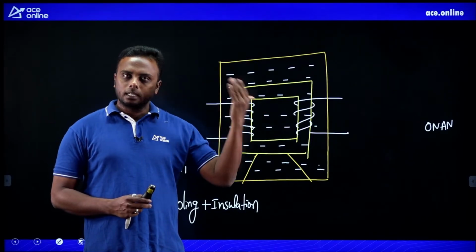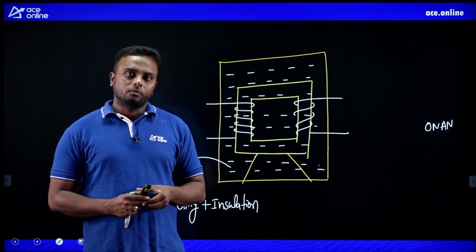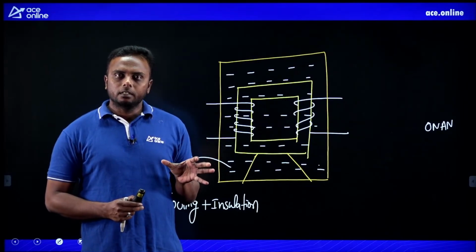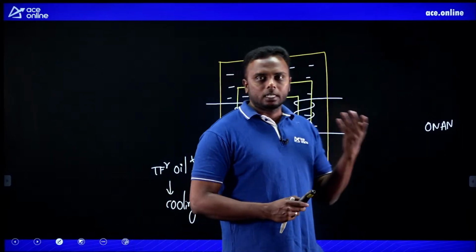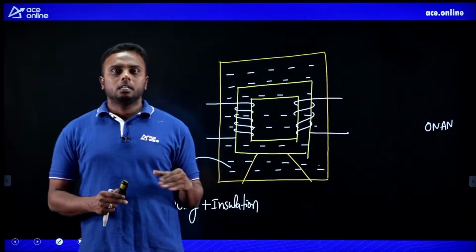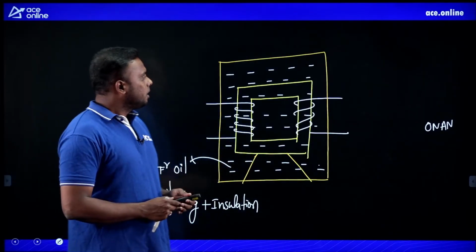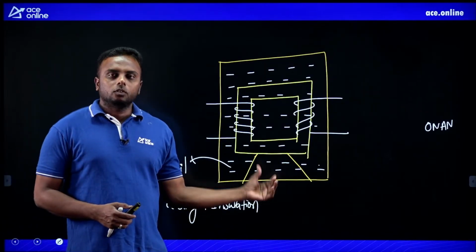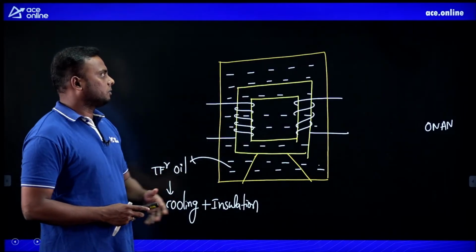But if you go to higher level transformers, power transformers with very high ratings, like 100 MVA, 10 MVA, 20 MVA, there we definitely need effective cooling, particularly at high voltage. Power transformers belong to higher voltage capacities, so they require better cooling than distribution transformers. Okay, next. The oil provides cooling and insulation for the outside body and the windings and core of the transformer.